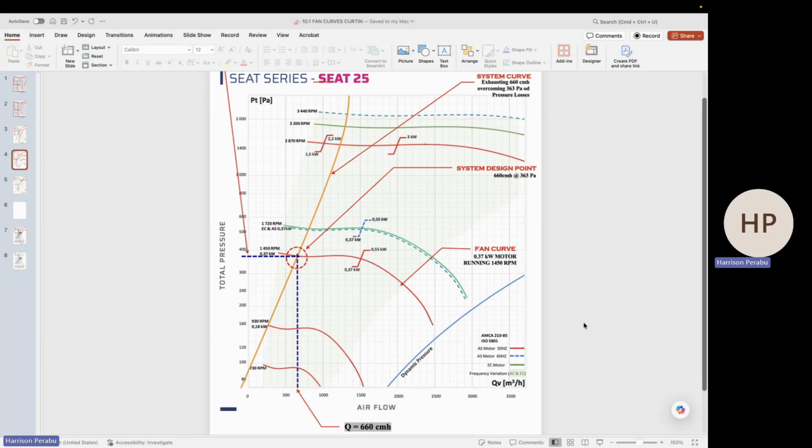So now we have a range of materials, a range of components, or this geometrical shape, better known as hood, in the array of five components of a ventilation system, comprising laboratory hood, extraction arms, ventilation hood, usually in the forms of canopy or a semi-enclosed enclosure like a booth. Then we also have custom-made hoods like slot hoods, depending on the plane of emission taking place, the working area and what's not.